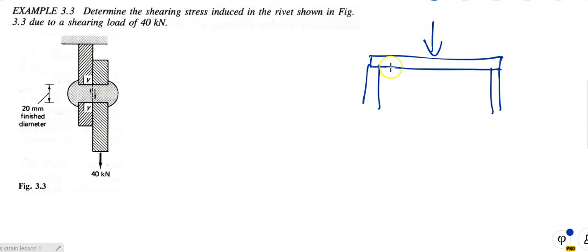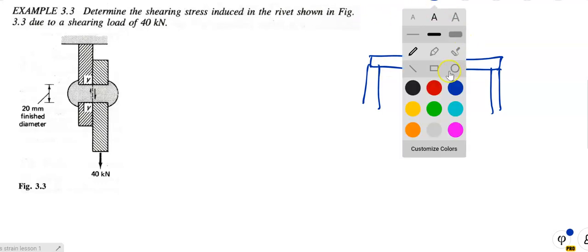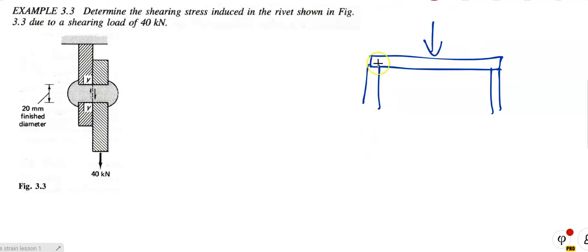What will want to happen is that this beam will want to break out right over there. This bit wants to fall through, and those two pieces there will want to stay on there. So at that plane there and that plane there, the beam is undergoing shearing stresses.